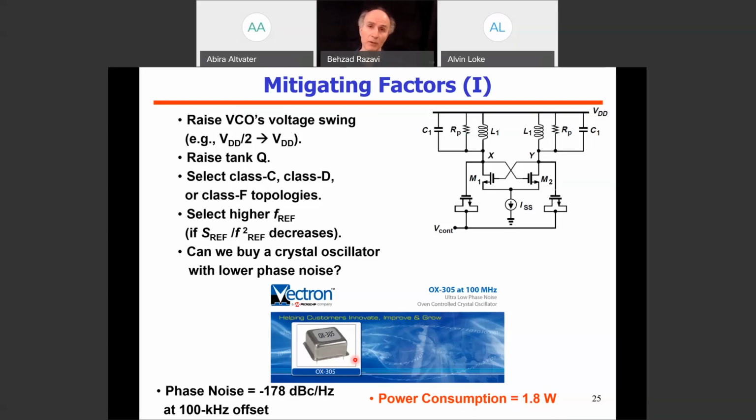If the reference phase noise is even higher, so let's say minus 160, then you can imagine how these power numbers will balloon into something completely unimaginable. So we do need to design crystal oscillators with phase noise numbers down in the minus 170 range. If we don't, we are in deeper trouble than what I have portrayed here. That calls for innovations in crystal oscillator design, PLL design, and even maybe jitter-tolerant A2D design before we reach these serious limits. Got it.